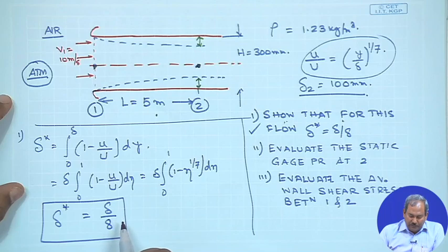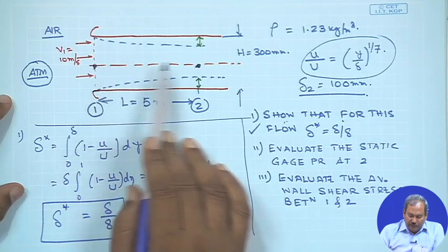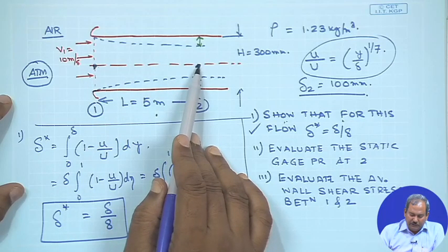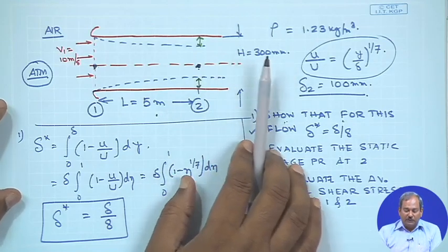But you also have to keep in mind that if I would like to find out what is the pressure at this point, I am going to use Bernoulli's equation, and Bernoulli's equation can only be used if the flow is inviscid in nature. But we have a situation here where there is a viscous flow taking place along the sides. The boundary layer is growing. So, the concept of displacement thickness will play a critical role in this.